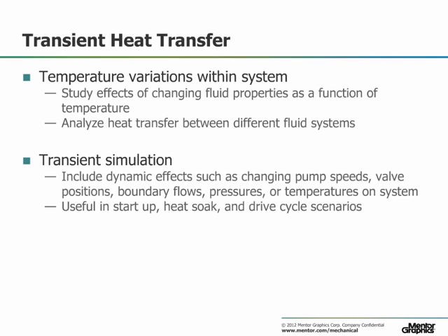In addition to providing pressure and flow results as seen in the previous simulation, transient heat transfer simulations will allow for the modeling of thermal energy being added to or removed from the system, as well as the varying of fluid properties as a function of temperature over time. This simulation type can account for the dynamic nature of thermostats, electric fans, varying pump speeds, varying engine loads, etc. This is typical for modeling startup, heat soak, and drive cycle scenarios.